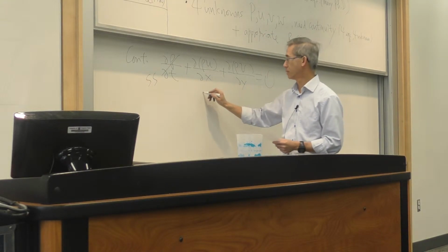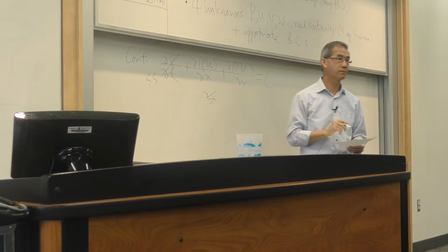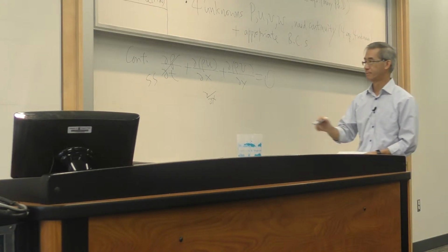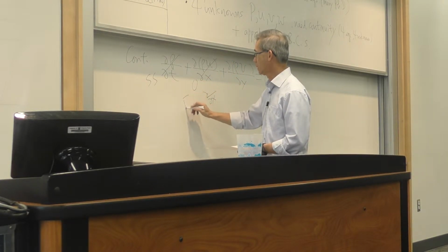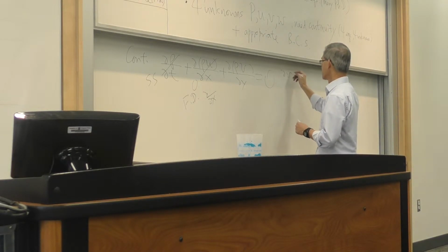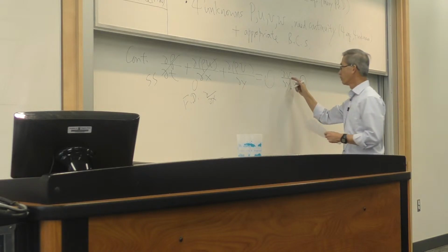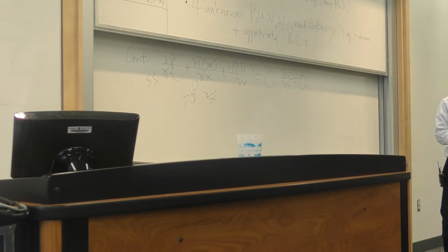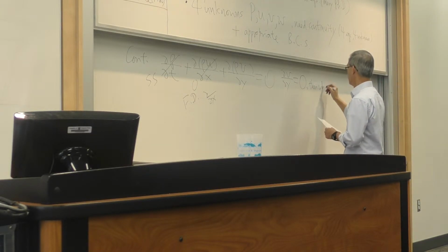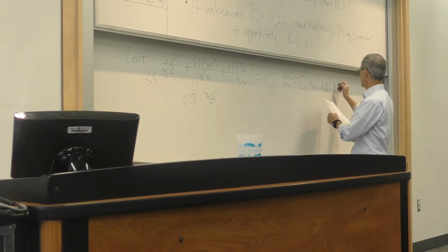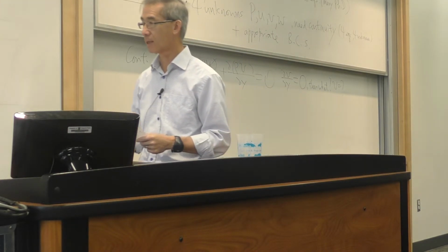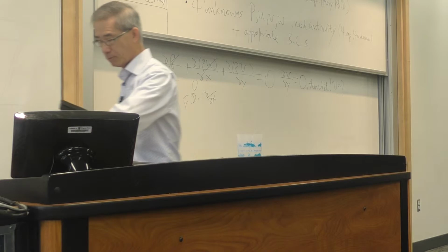Second term. Change of something with respect to x. What does it mean to you as fully developed? 0. Has to be 0. Reason? Fully developed. So what I'm left with is the fact that the derivative of velocity v in the y direction with respect to y is 0. Here's something you can think about. Applying the boundary condition, can you tell me what is v equal to? That's critical because that will further allow you to simplify the remaining x and y momentum equations.